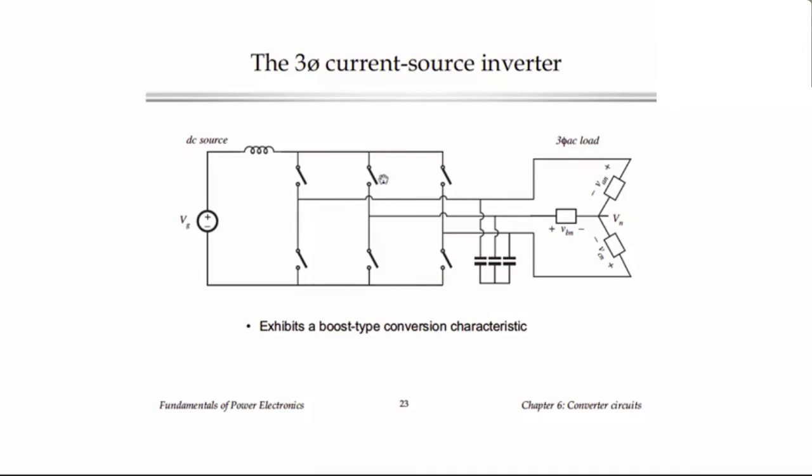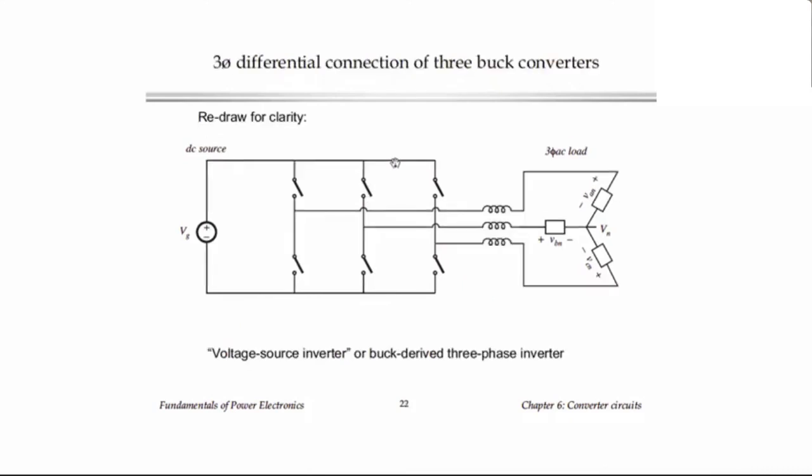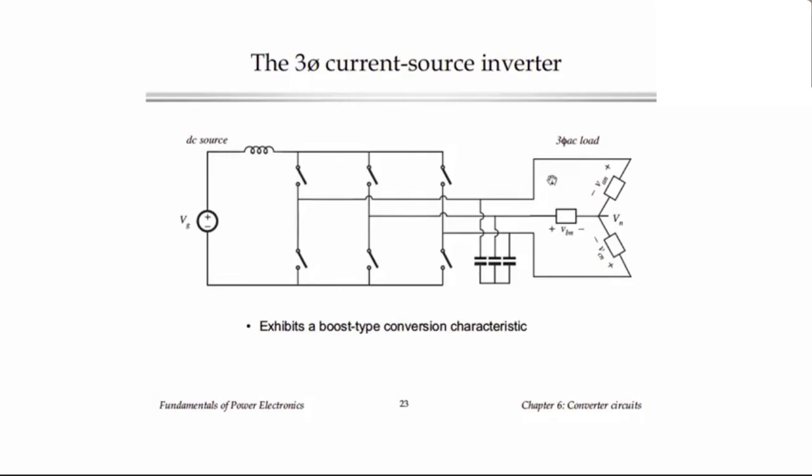In each of these circuits, I've drawn ideal switches, but of course we have to realize the switches carefully according to the procedures we've discussed in the previous lectures. So for this circuit, with the buck converters, our buck switches need to be current bidirectional switches because they conduct the AC output currents. And in the current source inverters, we need voltage bidirectional switches because they block the output voltages. But we've now already discussed how to do this, and we know how.